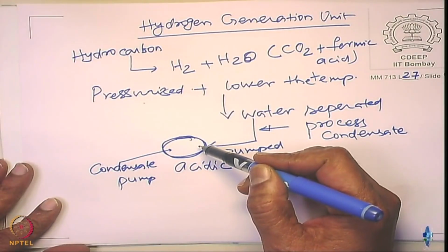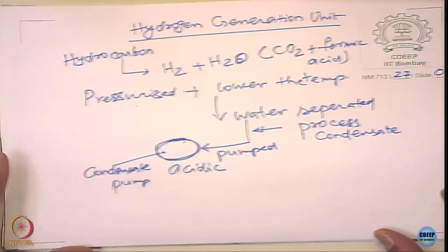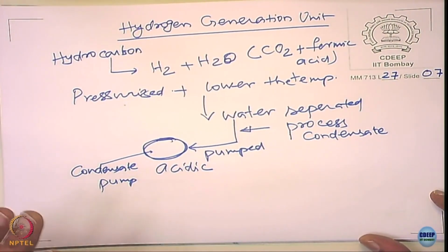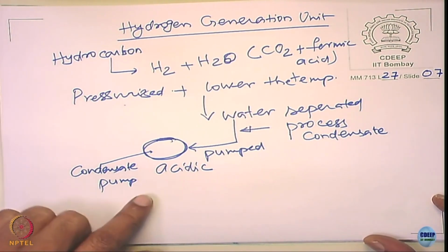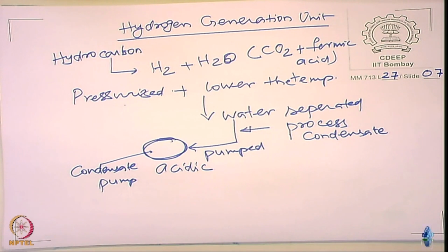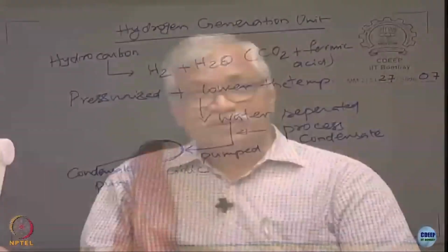The good point was they were having a standby pump, because these are the units that can go bad, and they do not want the system to be shut down, an unplanned shutdown. So they had a standby pump. Then they thought, okay, they probably knew that martensitic steel is not the same as martensitic stainless steel. Then they started operating one pump for about 3 hours, then moved to another one for another 3 hours. They kept shuttling between these two.